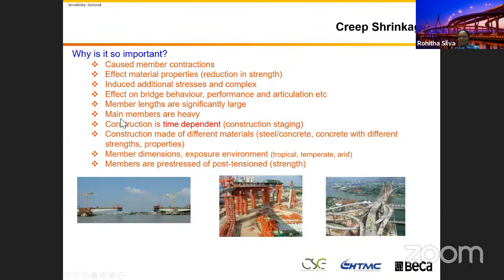And the main members are heavy in the structures because bridge structures are very heavy. This affects the deflection and adds a lot of stresses on the girder. And the construction is time dependent because creep is time dependent and shrinkage is time dependent, so the construction is time dependent. That will make your analysis sometimes a bit more complex.